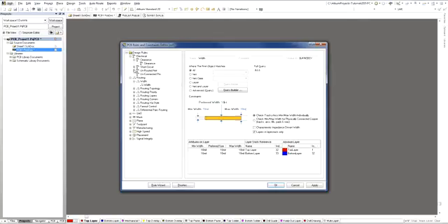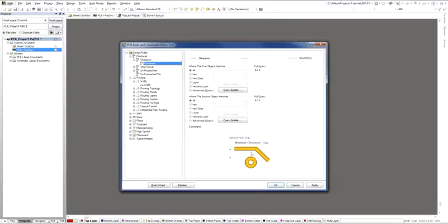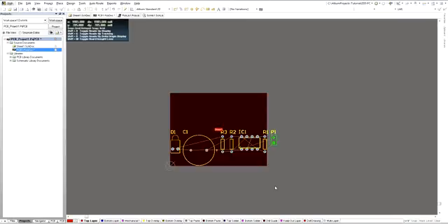You have a lot of different settings in here, but Altium Designer makes a nice schematic for you, so to speak, so you can change the clearances that you want. Let's say you want to set this to 20, and then you press enter, and there you go. You should really go through all of these and make sure that they're correct with your standards as well as the manufacturer's, to avoid any overcharges on your orders. So you click apply, click OK, and you're done with that.